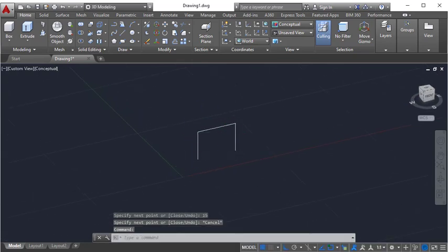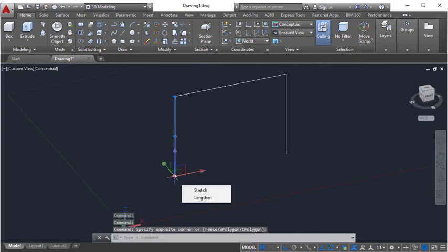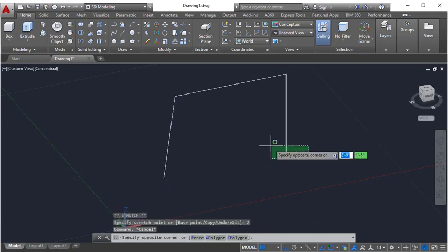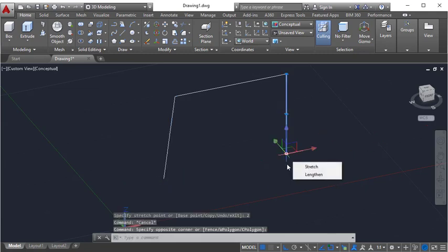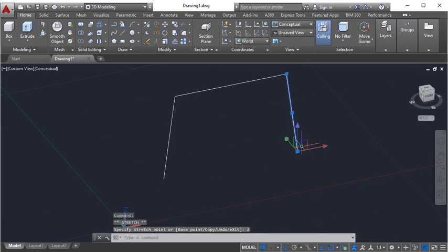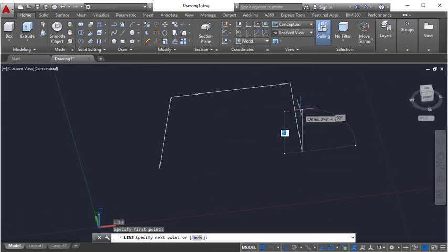This is like two legs, just for design purposes, I'm making a little bit of a model. So for that, in this direction 2 inches, and this one also snap it here. Automatically the gizmo will change, and I will select the x-axis and move it 2 inches. Next step, I will draw one more line in the z-axis. Make sure you snap it in the z-axis and use 32 inches.